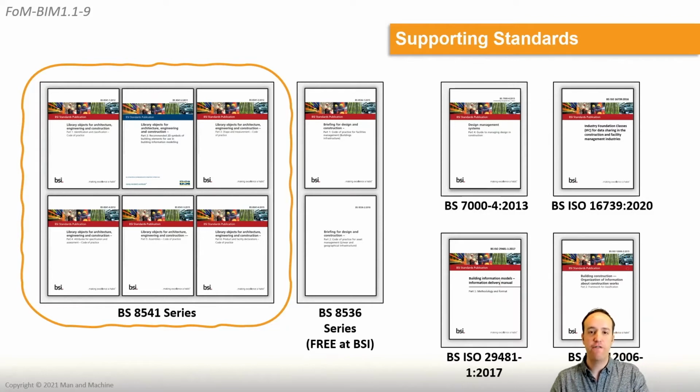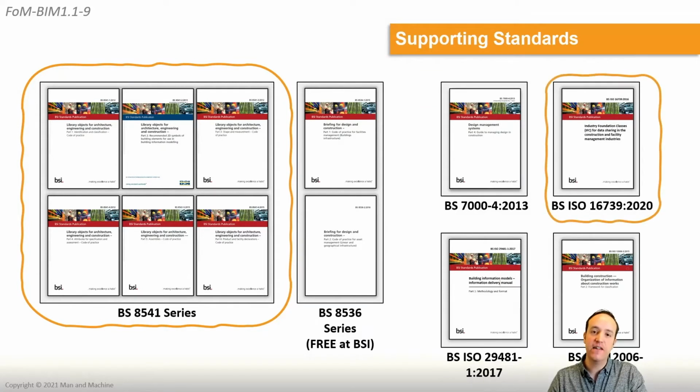Firstly, the BS 8541. That explains how you should be naming and modeling your components for use in a digital construction world. We'll talk about those in a second. You then have ISO 16739, which talks about the Industry Foundation Class. The only reason I flag that one is because Inventor, for the past few years, has been able to export IFC files. If you're being asked to produce IFC files on a project and you're collaborating, you need to read and understand that standard because it will explain how you should be using that IFC and it will help you be compliant on that project.